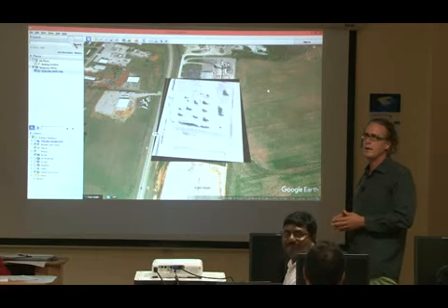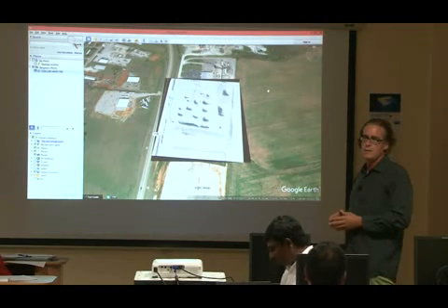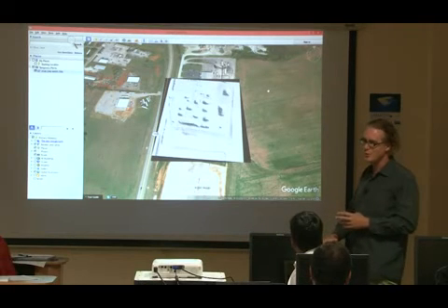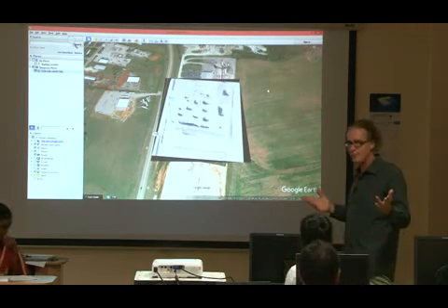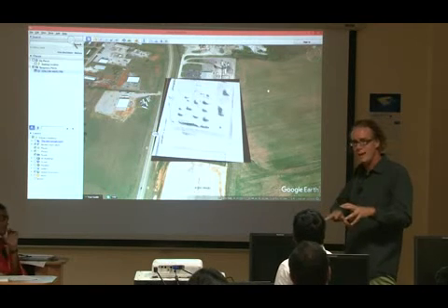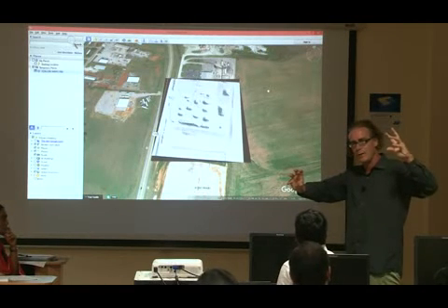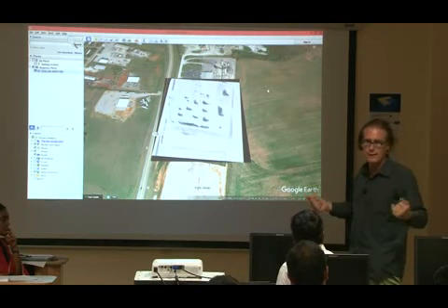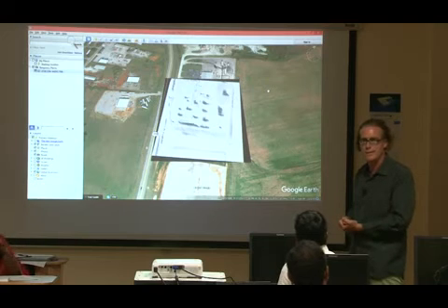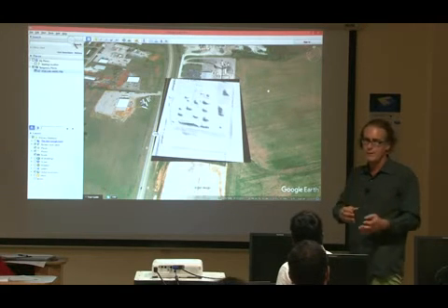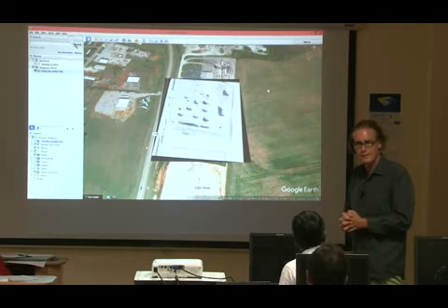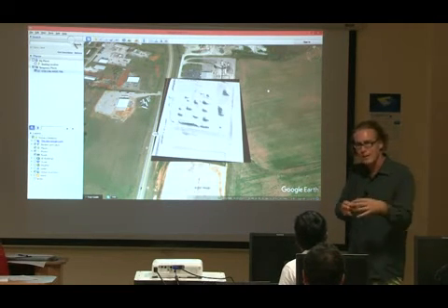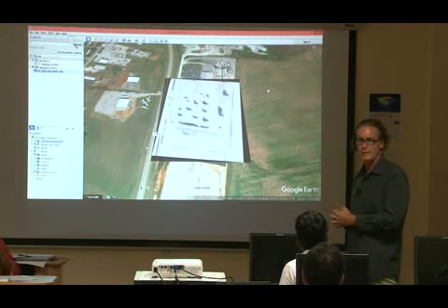Well, I don't think so. Interesting. I've never seen any study that shows geometry deformation under smoke. Not saying it doesn't happen. But what does happen is that all the first returns get stuck in the smoke, and even if the LiDAR penetrates, it penetrates much less under smoke because it reaches the actual terrain with much less intensity. So if you directly compare with some kind of typical techniques where groups of pixels are compared to other groups of pixels in your reference plots, it won't work in all areas affected by smoke.